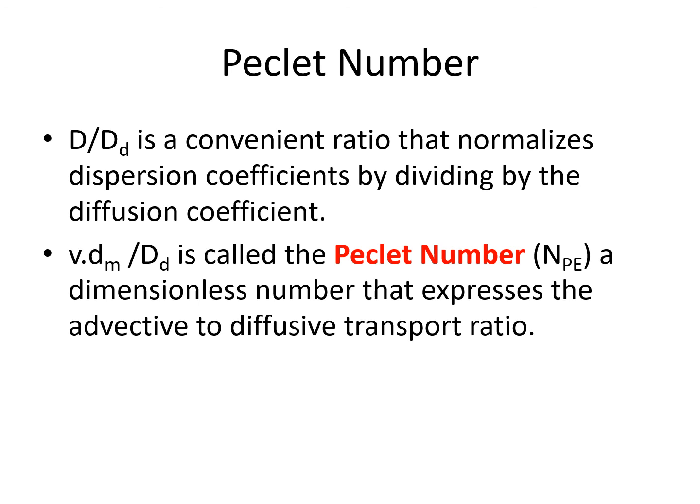Whether it will be diffused or dispersed, both phenomena can take place. For diffusion we have one coefficient, and for dispersion the other coefficient, and both are interlinked. The ratio between these two coefficients gives the value of the Peclet number, which defines how this cross-sectional area of the layer will exhibit its behavior. It all depends upon the Peclet number.